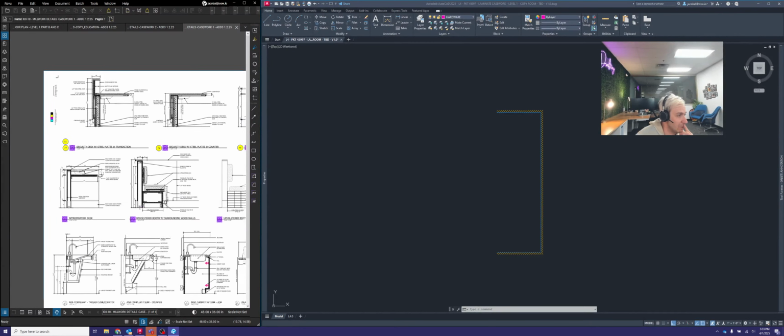So we made an inference based on a different section view with a 24-inch deep counter. And then we also looked at what we did before on our last L1 drawing, and we did have a 24-inch deep counter there as well. So we scaled it, we looked at our old drawing, and we looked at another section view on the drawing set. We used those three things to make our best guesstimate, being that we're thinking these are 24-inch deep counters here.